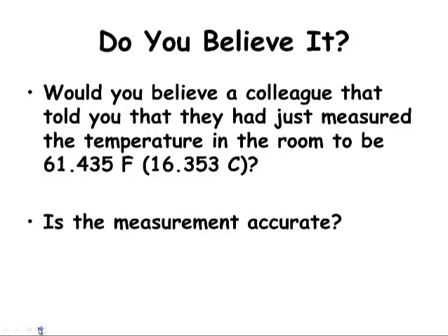The first question is, what do I think the room temperature is? Some people call this a sanity check or reality check. 61 degrees Fahrenheit is fairly cool. Do I feel cool? If not, maybe the sensor used isn't reading correctly. Is the room heated? Air conditioned? If the windows are open, what was the predicted ambient temperature? Is sunlight heating the room?